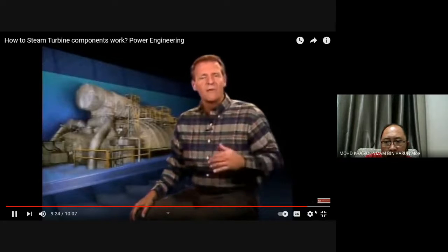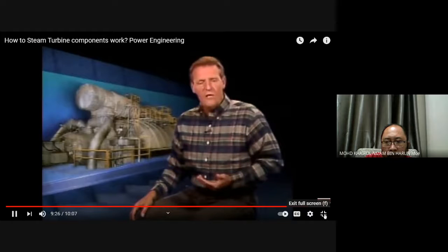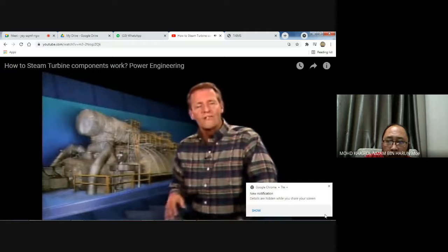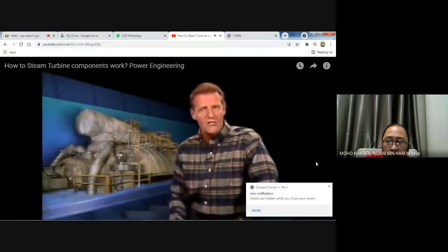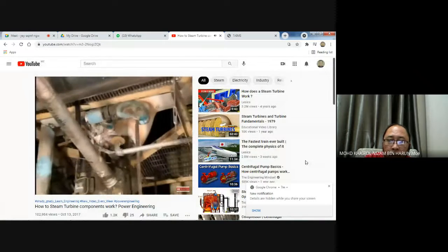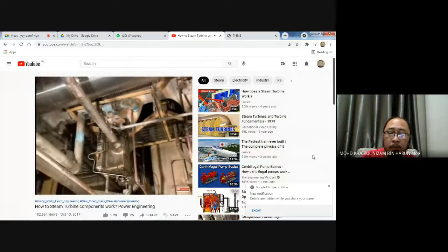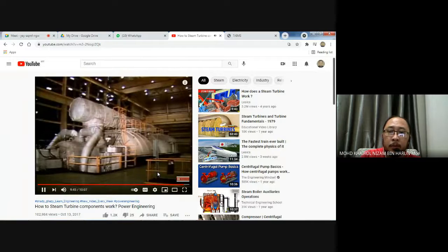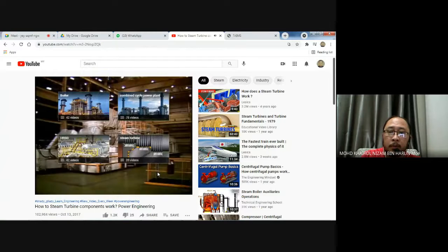If the turbine begins to speed up, the control valves will compensate by closing. However, there is still a great deal of steam in the reheater section of the boiler. This steam will continue to flow through the turbine, causing it to speed up. To prevent overspeeding, the intercept valves close, cutting off steam from the reheater. If for some reason the speed continues to increase, the turbine trips.